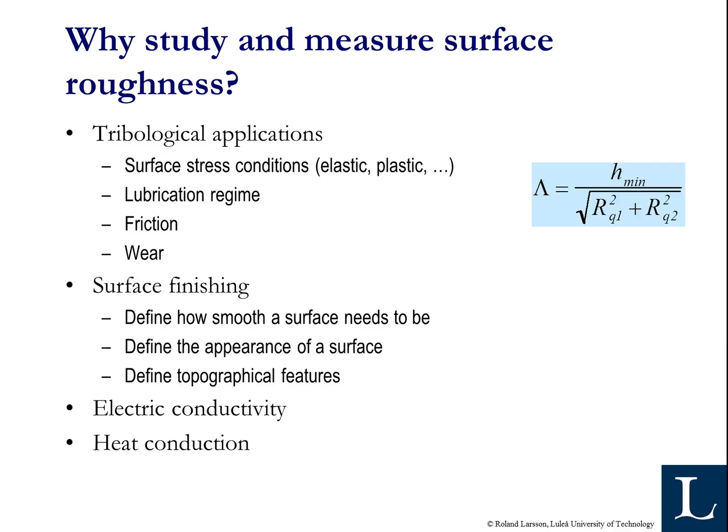Okay, but why study and measure roughness then? Well, we have been discussing the tribological applications, of course, since the roughness controls how much the asperities penetrate the other surface. They also influence the surface stress and then also the wear risk. And as we discussed, it influences the lubrication regime, and it also influences the friction and the wear.